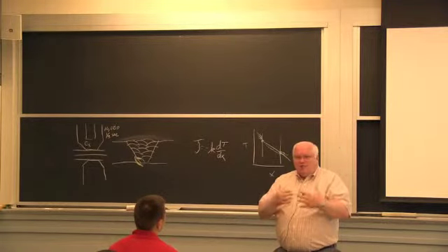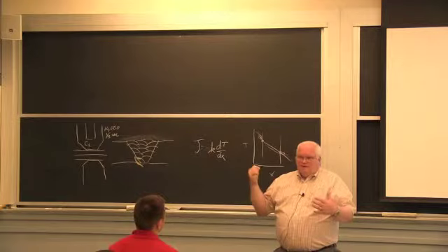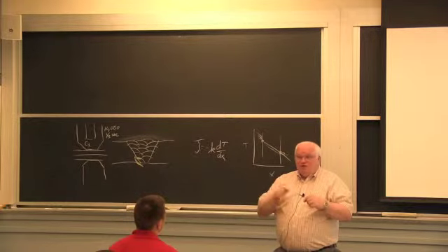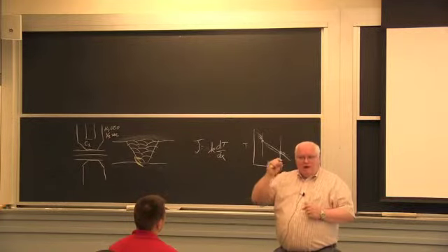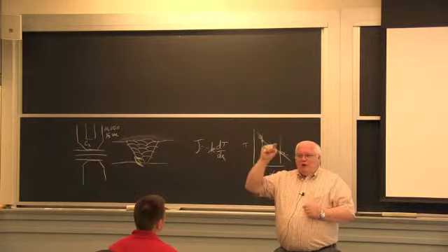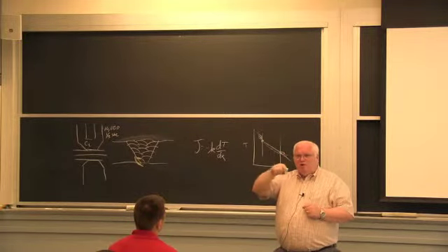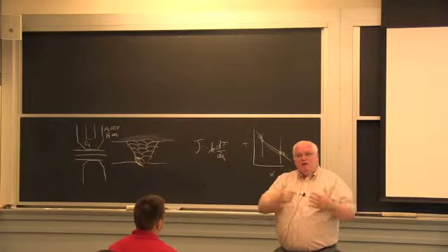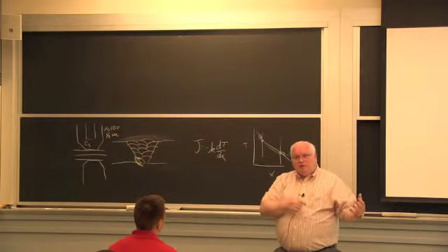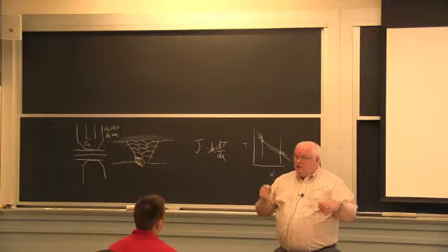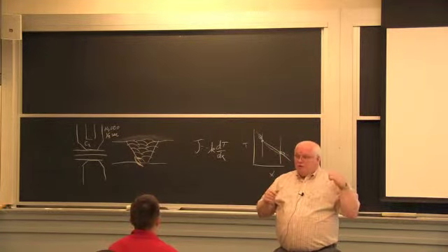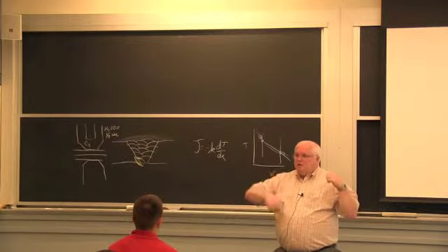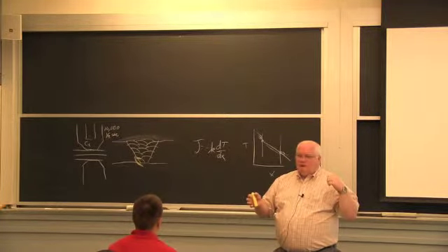But nonetheless, I proved that, and if you do the calculation, you can prove that during that 1/3 of a second, it doesn't matter whether you got water up there or not, but your point is absolutely correct. Yeah, it cools it off in between the next weld, which might be 2 or 3 seconds later. So if you do the calculation and you put in, instead of 1/3 of a second, 3 seconds, you'll find, oh yeah, I did cool the tip off in between, okay?